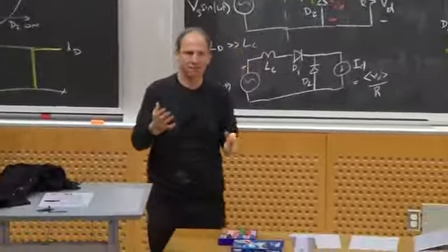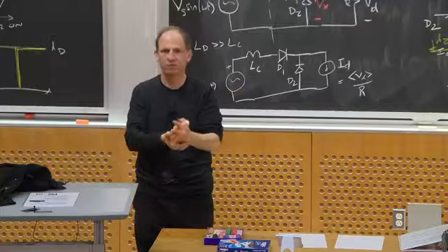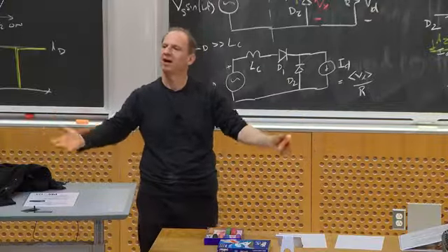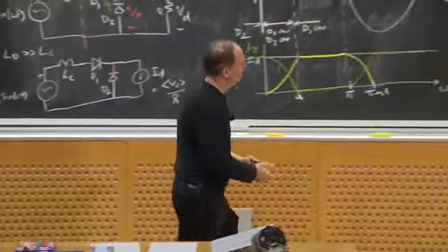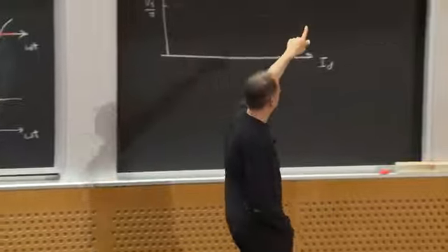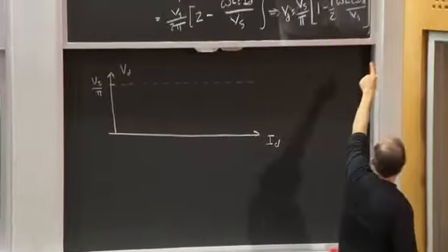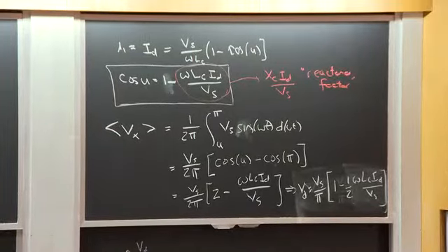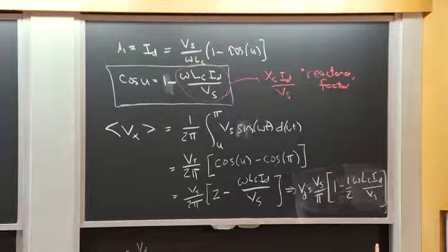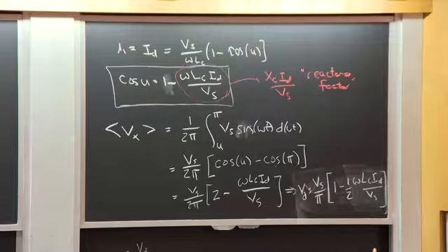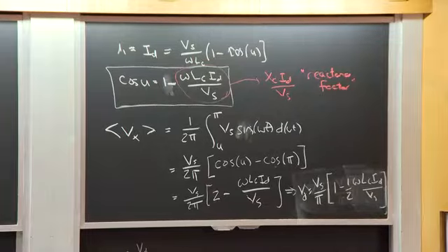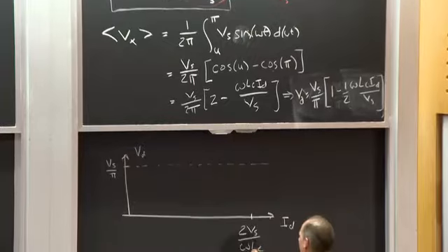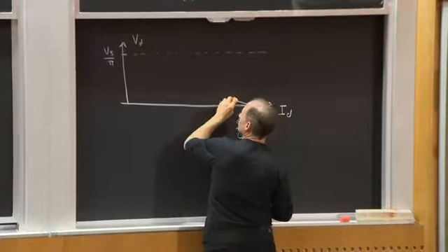So I could kind of reliably generate that AC voltage, rectify it, and I'd get what I want, right? And very typically, I'm trying to get a voltage out of a system. What this says is that the voltage that I get, Vd, actually droops versus current, right? And in fact, I'm going to get 0 voltage once the current gets to be equal to 2 Vs over omega LC. Right? So actually, my actual characteristic looks like this.